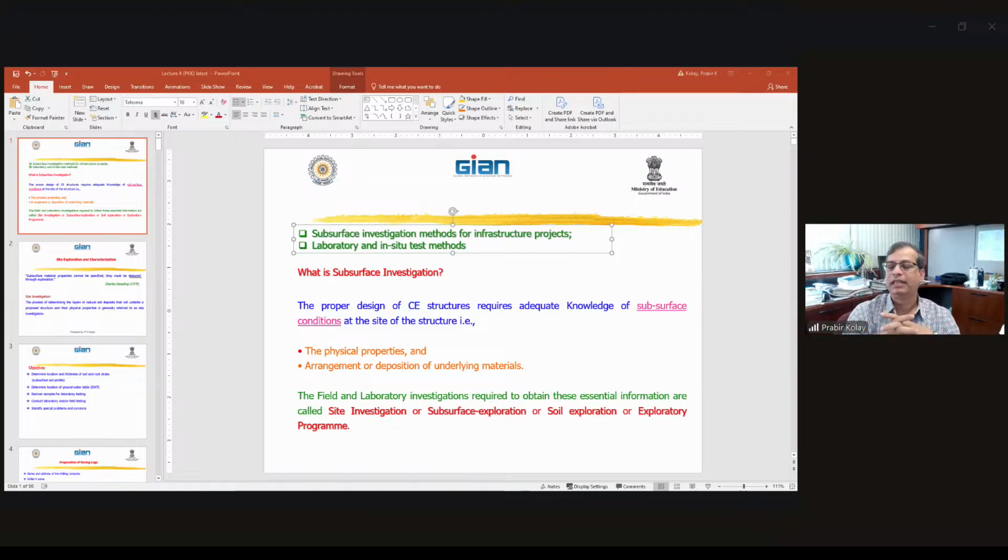So that is the disadvantages. And also, although it will give you everything, it will give you a graph. If the cone penetration end bearing is higher, it will give you a higher value, meaning it's sand, or more sandy or cohesionless soil. If the sleeve friction is more, it will show automatically on the computer screen itself.